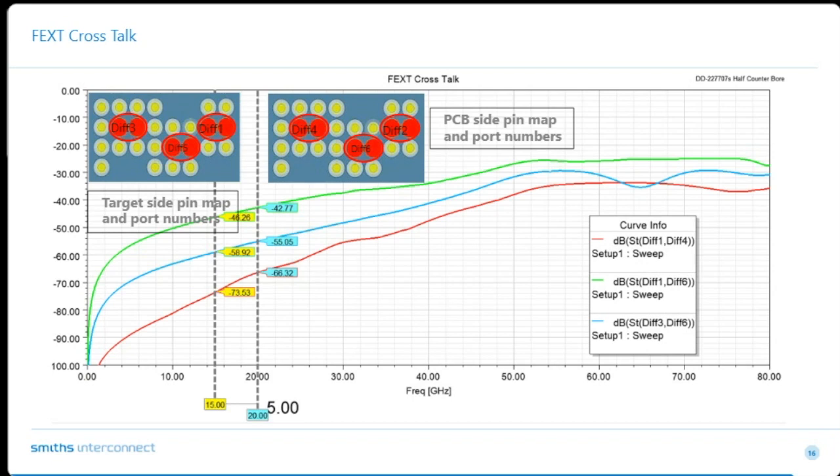So you have a different probe configuration, or would you design a new pin? If we don't have the pin available at the moment, like I said, we have a few. We would start with the one that best targets that impedance target to get the smoothest signal through with the best return loss and insertion loss.